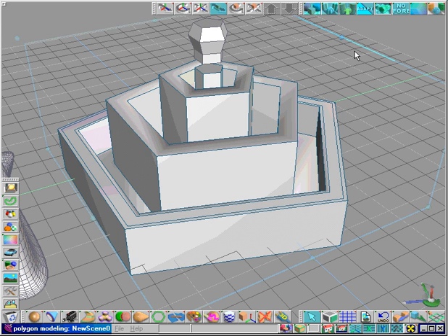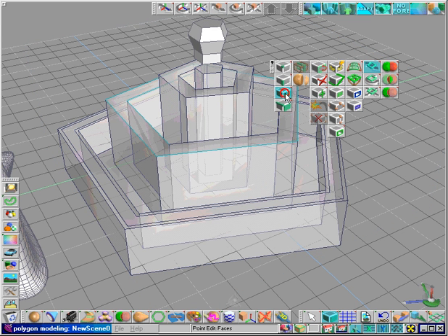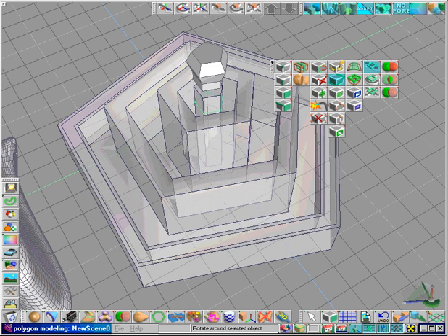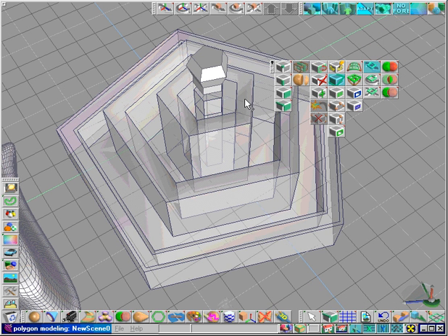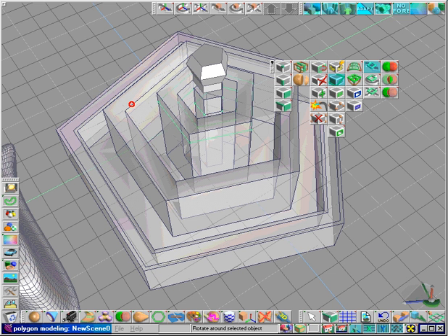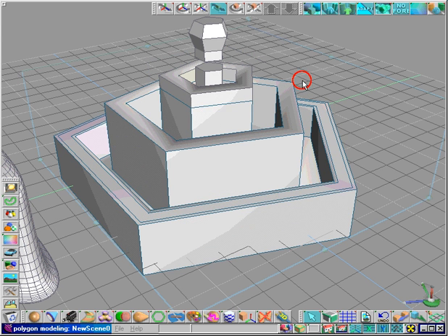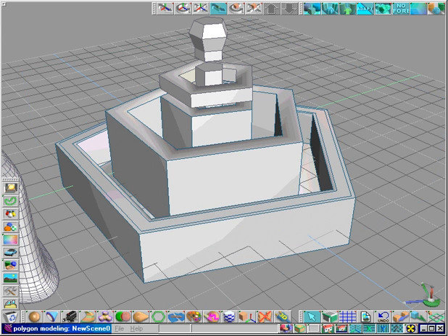We will select the top face and use the Object Slice tool again to create a new copy and move it down. Notice that the new edges are below the top level of the next outer ring. With nothing highlighted, we will use the Polygon Slice tool to select the new vertices, but this time we will hold down the Control key on the third click. This causes the slice to pass through the entire object. A fourth click on the top portion will highlight everything above the slice line. Using the Separate tool, we'll split the selection off.